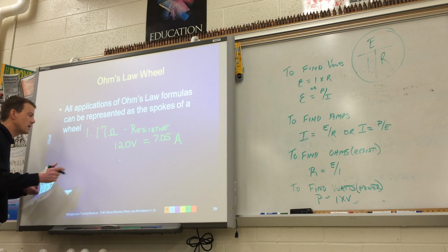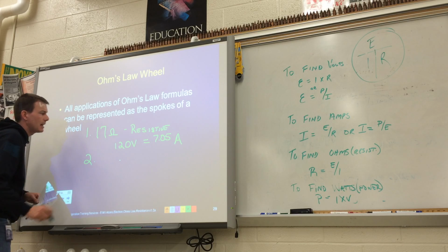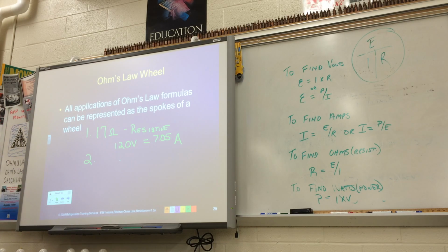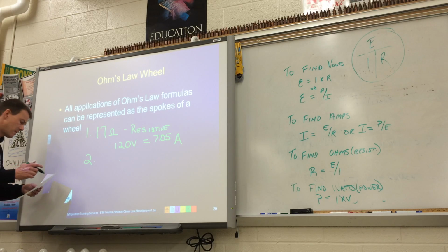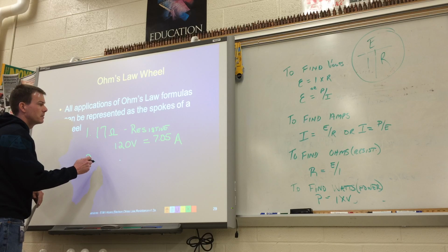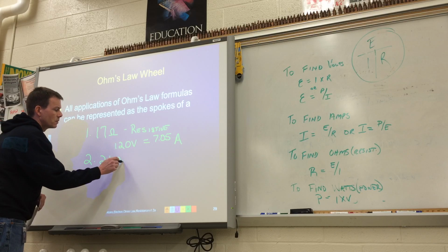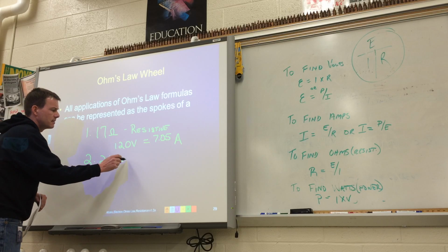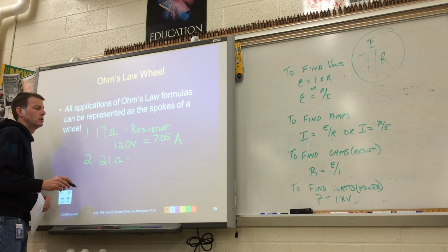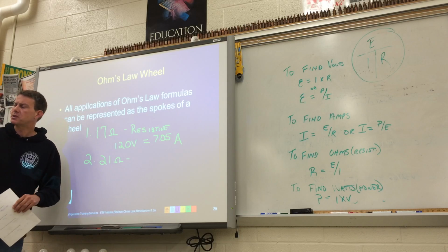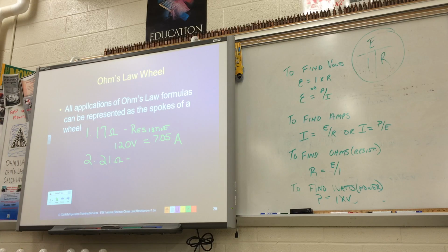All right, so we got another one. What about the cold lamp or the hot lamp? This one was cold. What happened to the resistance when the lamp went hot? It went up to what? What's the number you got for the hot one? 21.9. All right, so it went up to 21 ohms. What type of load is that? It's a light bulb. So there's a resistive load, an inductive load, and a capacitive load. What type of load is a light bulb?